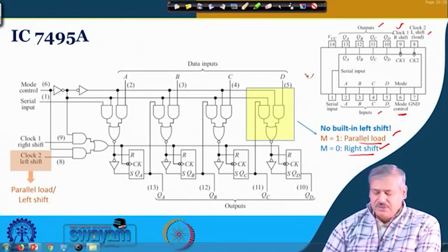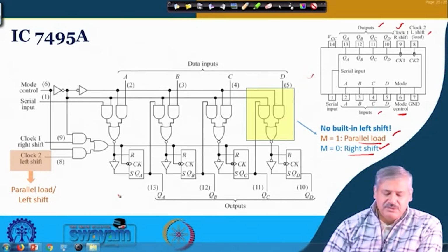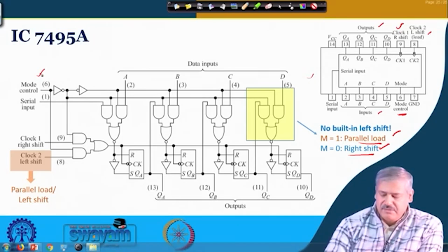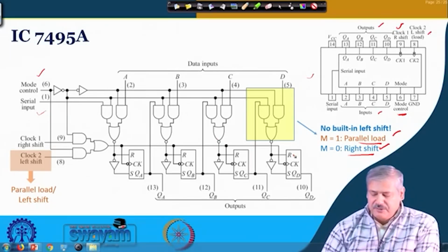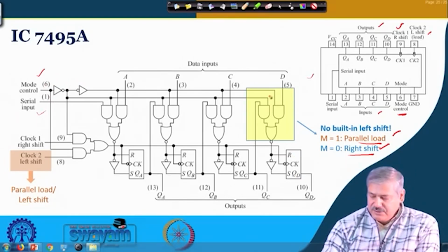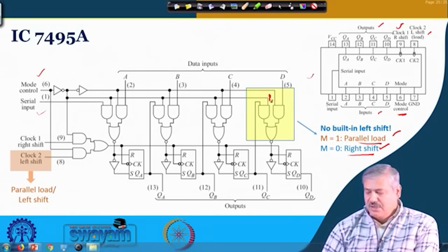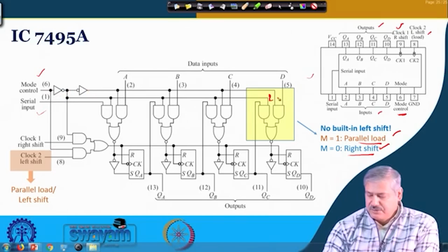Okay. So, this is again made through SR flip flops, and this is the mode control, right. This is the serial input, and if you look at just one of them over here, with mode equal to 1, okay, 1 comes here. So, this is your 1, this is 1, this is 0. Another inverter, so this is 1. So, this AND gate is now active, and the other AND gate input will be 0.